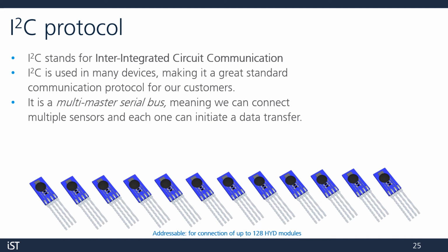It's a multi-master serial bus, which means we can connect multiple addressable sensors, and each one can initiate data transfer. As I mentioned before, HYTs are addressable, meaning we can connect up to 128 HYTs to a single bus.